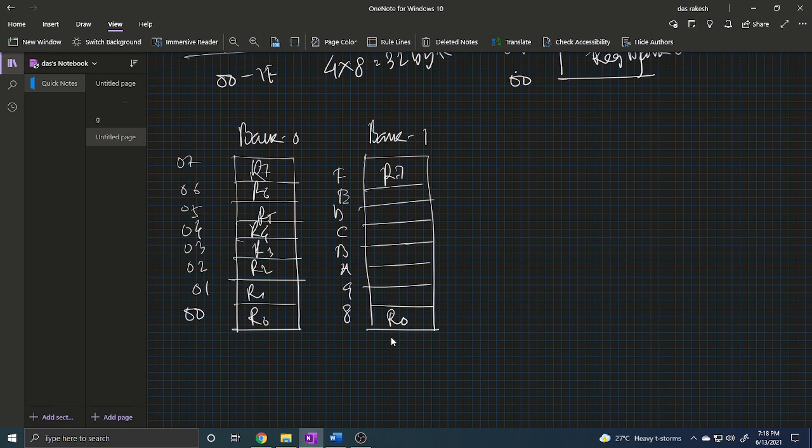Okay, so when powered up, the stack pointer register contains 07, which means RAM location 08 is the first location used for the stack by the 8051. Because if the stack pointer is at 07 when the 8051 is powered up, then the next location, that means 08, is used as the first location by the stack.